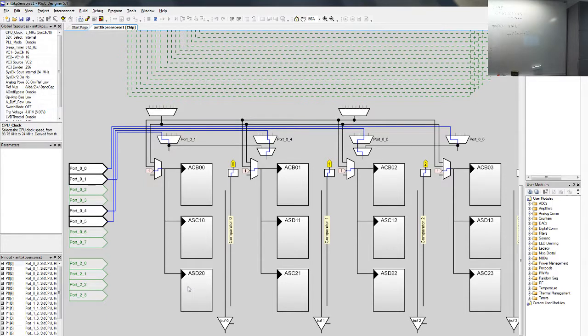But where you need the tuning is these resistors. And now this switch capacitor technology combined with that means that you can make analog filters that you can tune. All right, and there is a tool actually to tune them. Good. So the technology is there in the blocks. There are continuous time blocks, which are basically just amplifiers, and then switch capacitor blocks that can be tuned to do some filtering or A to D conversions.